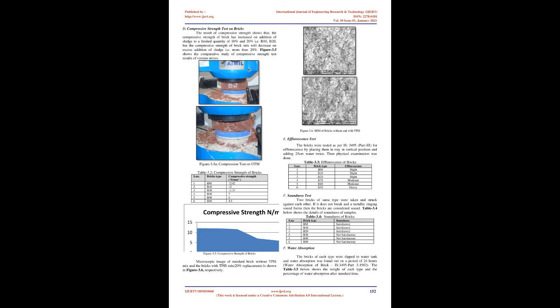The thermal conductivity of the brick decreases due to the presence of TPIS, which has low thermal conductivity. In the long run, it can attract potential for development. Most tropical areas desire low thermal conductivity construction materials to optimize the load of cooling or heating within the space of the building.